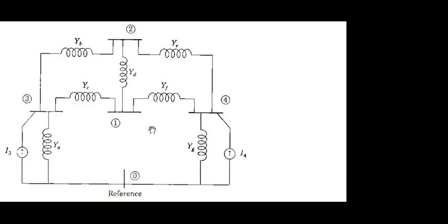The reactance impedance information diagram is already completed. This is the new one. If it is the circuit, try to write the nodal equation for nodes 1 and 3 as well as 2 and 4, considering the lowermost node as 0 or the reference node.